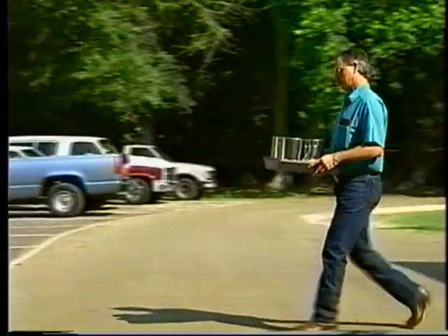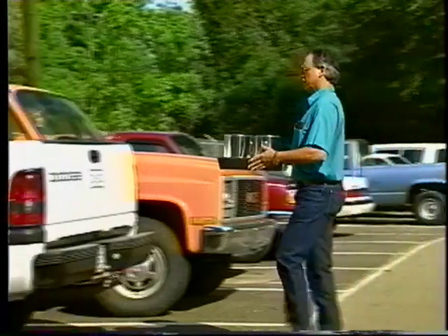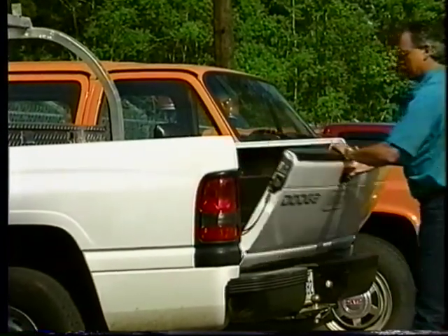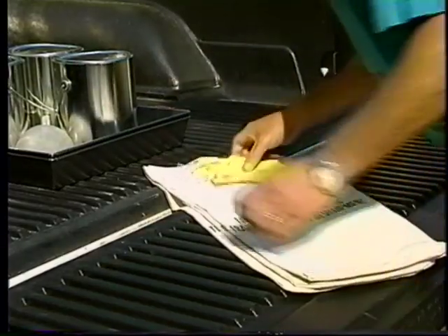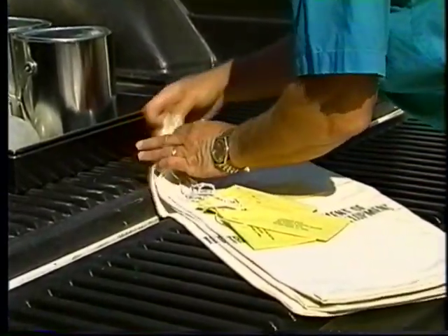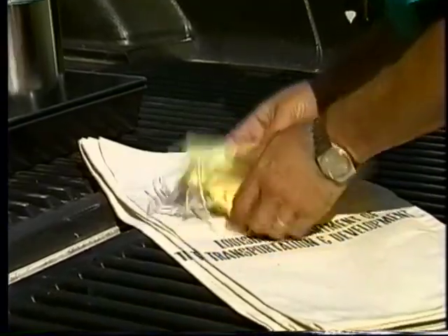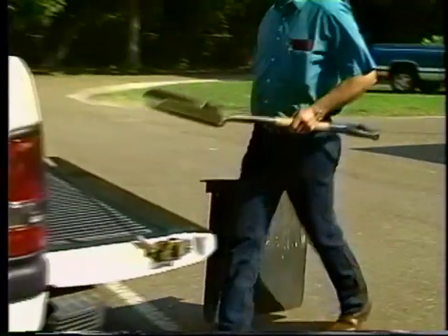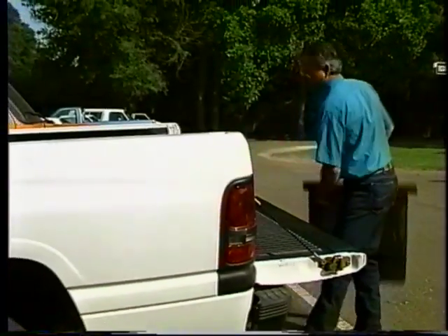Before sampling can begin, you must assemble all the right equipment. The forms and tools used must be appropriate for the type of material and how it is stored. You will always need sampling sacks and string to contain the sample while transporting and storing it before testing. You will need a sampling shovel and shield for sampling from stockpiles, barges, windrows, railroad cars, and trucks.